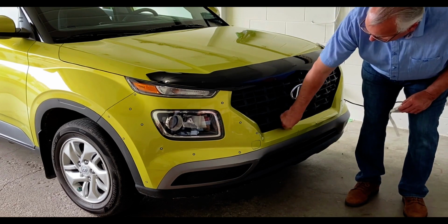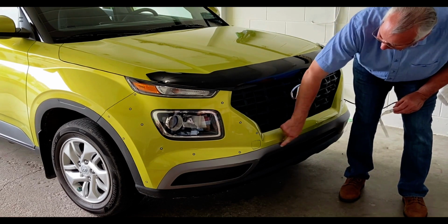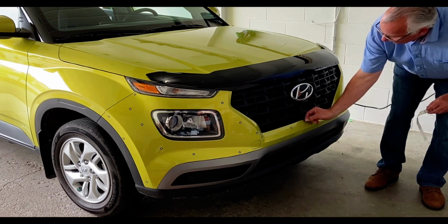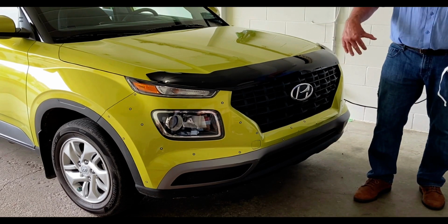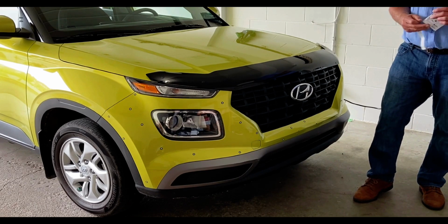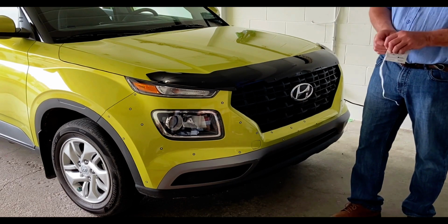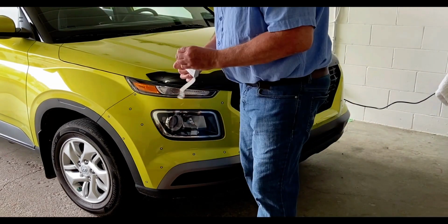We're going to only scan half of this car bumper because it's symmetrical and we can easily mirror it. And you want to make sure that the scanning targets are not placed on areas that are going to be excluded from the scan. We'll just put a few more targets down here, make sure that we got good coverage. There we go. And you'll get a feel for how many targets to use.